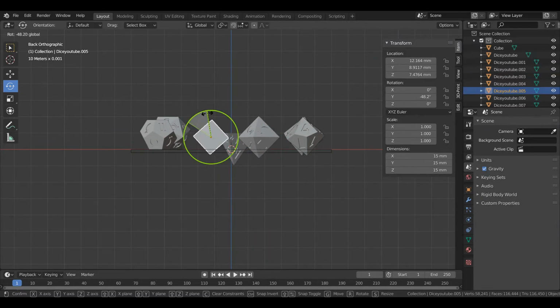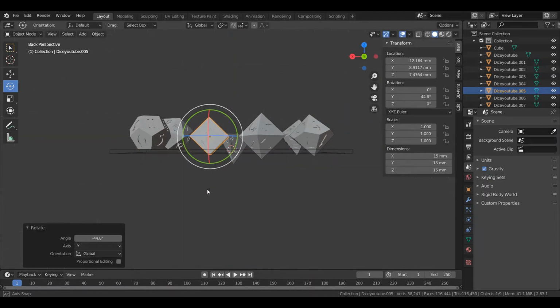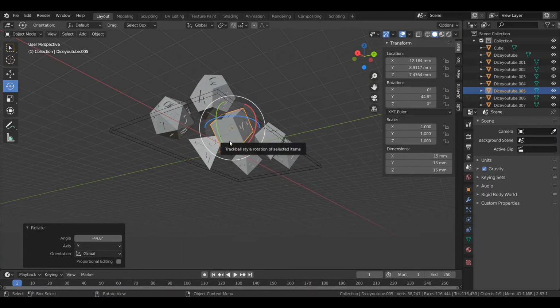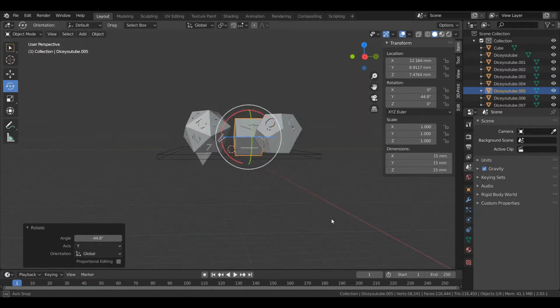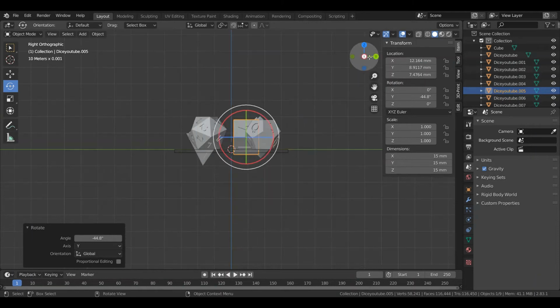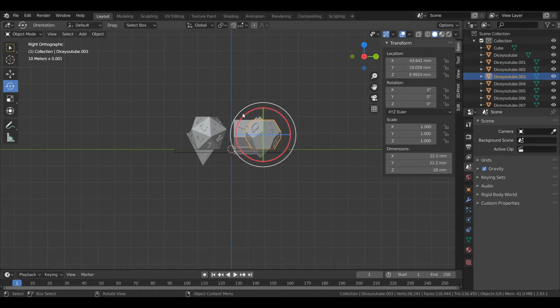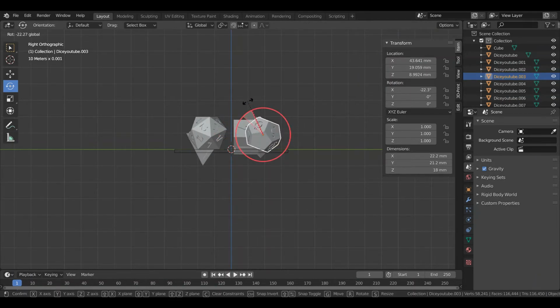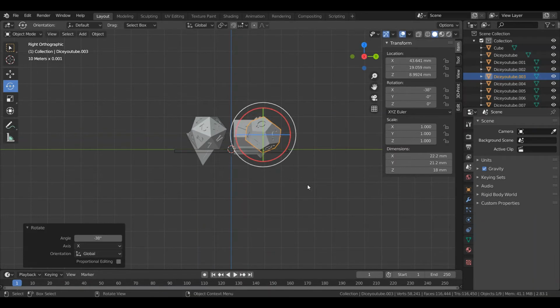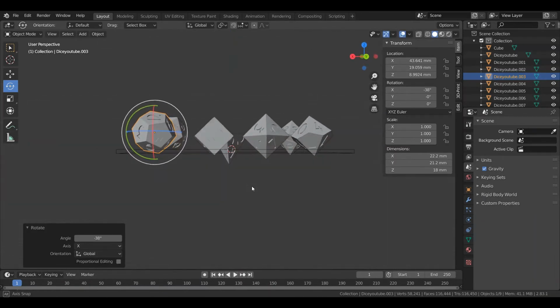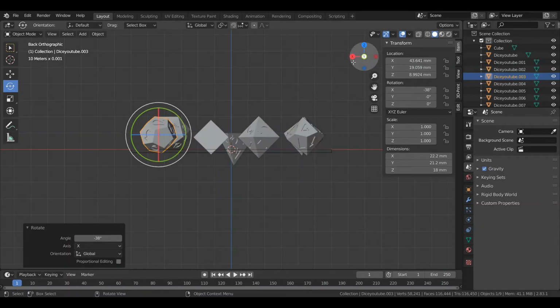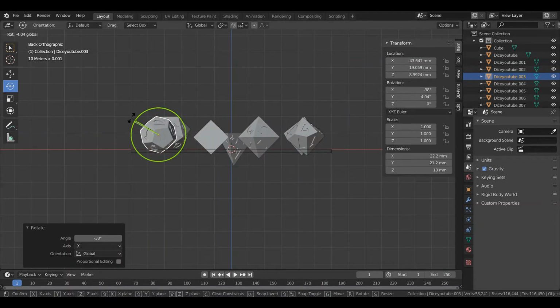And the D6, I'm not going to put on a point, I'm just going to rotate it on an edge. That's what I found prints best for me. When I was printing them on a point, this point that's closest to the build plate always came out elongated, and I tried a lot of different resins, a lot of different exposure settings, and I just couldn't get that to print properly, so I started doing it on the edge, and that solved literally all of my issues. So I just print them like that now.